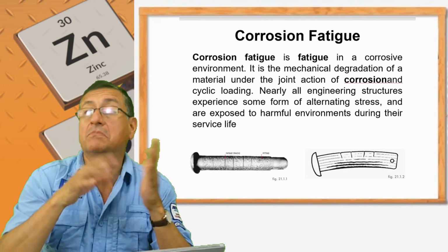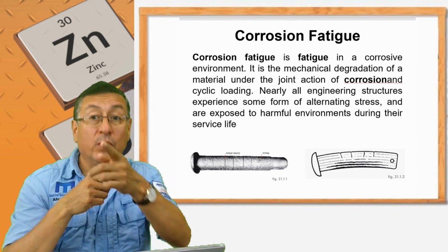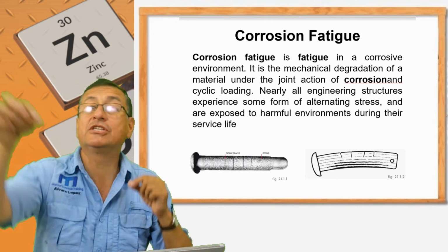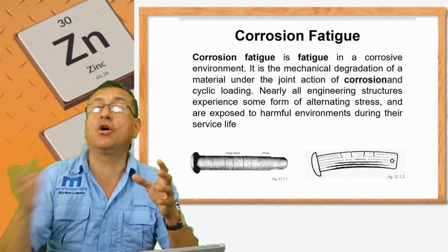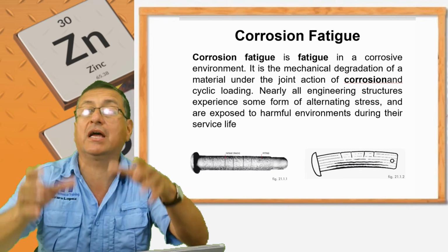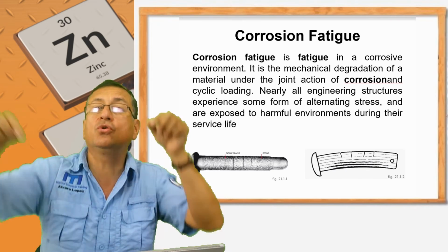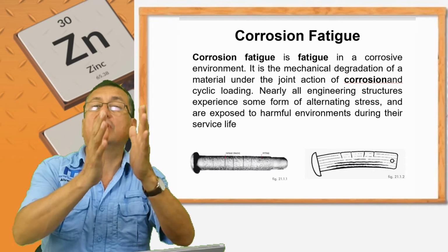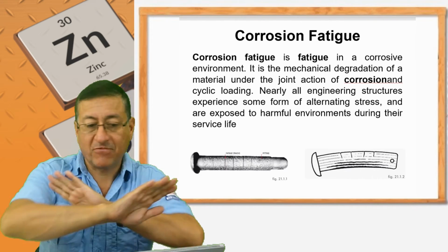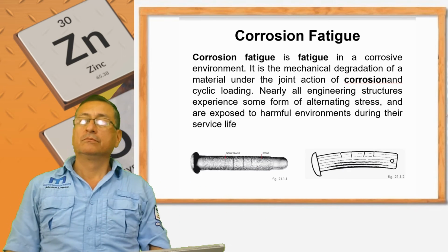And suddenly, twice per year, with the silver chloride electrode, check the condition of the water and your boat in that specific marina or in that dock. Use the electrode to verify if your bonding is appropriate. Finito. This is the rule.